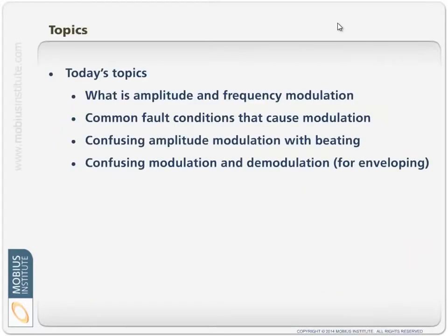In this presentation we're going to look at modulation, amplitude and frequency modulation, and we're going to look at some common fault conditions that cause modulation in gears, bearings, electric motors, and might mention some others. I'm going to attempt to clarify what the difference is between amplitude modulation and beating, and clarify what the difference is between modulation, frequency and amplitude modulation that we see in machines, and the demodulation technique used in enveloping and so on. They might seem like they're related, but they're actually not.